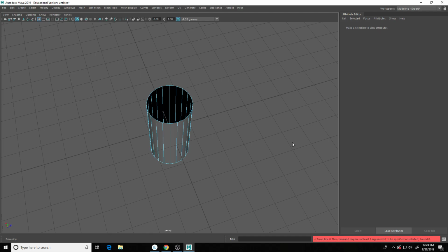So if I give you 500 instructions right now, and each one of those instructions has 3 points of reference, X, Y, and Z, how many of those do you think you can remember before you scream at me to stop talking? I'd say 2 or 3. But after that, you just get mad, right? What Maya is doing is remembering everything that you did to 3 points of location. It will scream at you, but it doesn't yell, it just crashes. Does that make sense? So deleting my history before moving on to my next thing is important.